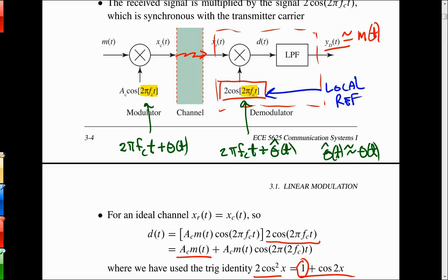Bluetooth actually uses a form of FSK. It's called Gaussian FSK, but it's still an FSK kind of scheme, frequency shift keying. It's been used for a very, very long time, and it's more sophisticated in today's world, but the old-fashioned one was just two tones. And that doesn't have to be coherent. It can be coherent, but you can receive it non-coherently. And that has the advantage that you don't have to have the extra processing at the receiver to have a tracking carrier, which means it's good for environments where it's too difficult to track the carrier phase.